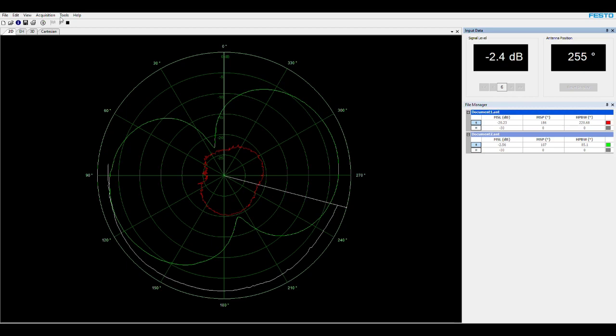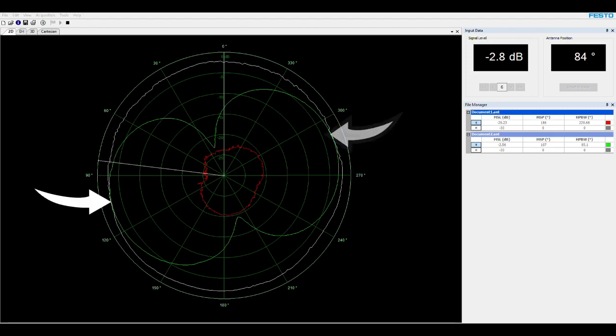Of course, the antenna itself is completely symmetric in this plane, but remember that we have a cable feeding the antenna and other things, the room itself, so we may not have a completely symmetric situation. But as you see, the result is actually very nice. It's like a circle, and you see that in this plane it's actually omnidirectional. This is in contrast to the E plane, where we had the donut shape and we were directional. Now if you look at the marker, it was showing the maximum of the signal for both cases earlier, and as you see, they're on top of each other.